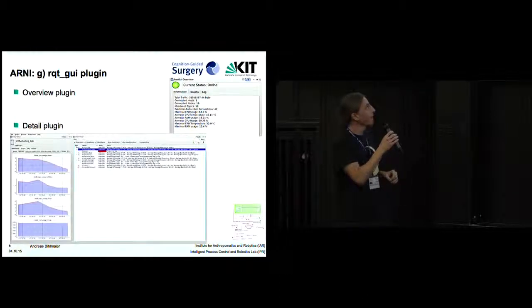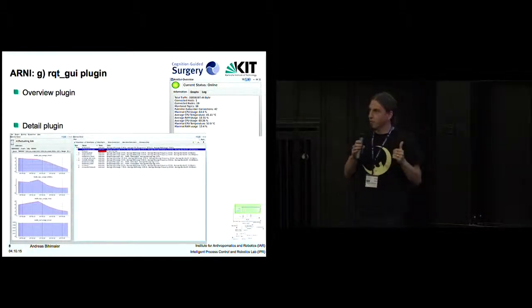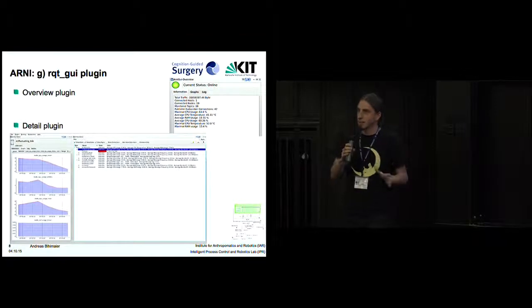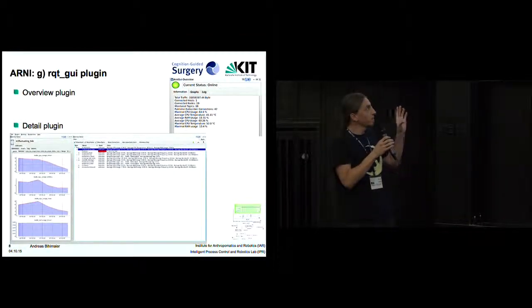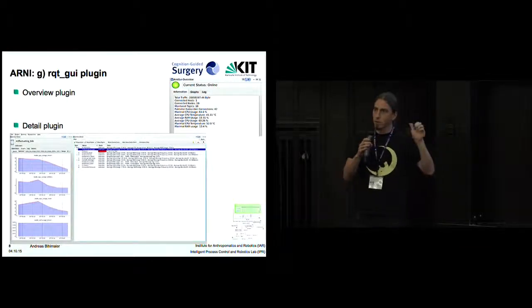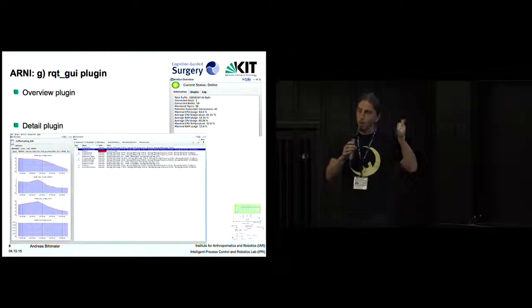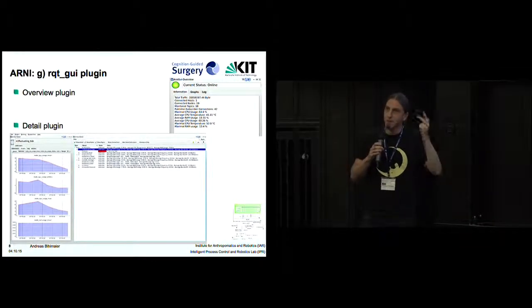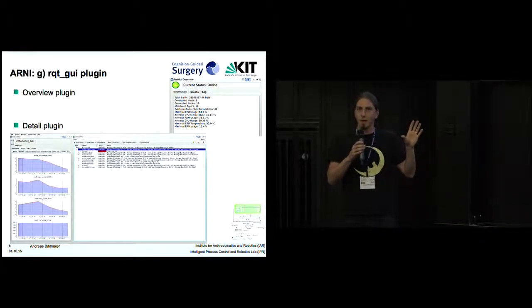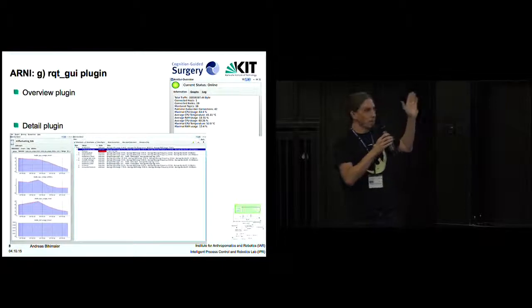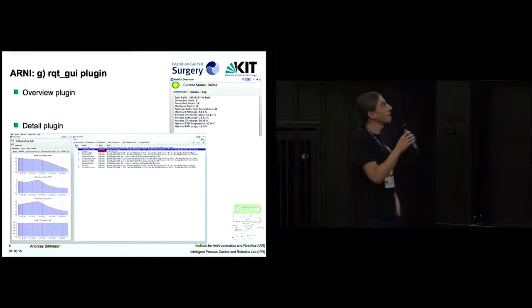Next slide, please. And then what you can use out of the box without starting any additional nodes, if you're running ROS beyond Indigo, is a GUI which gives you this central overview of all your nodes, all your hosts, nodes, topics and connections going on in your ROS network in one central RQT plugin, together with some nice historical plots about the data.